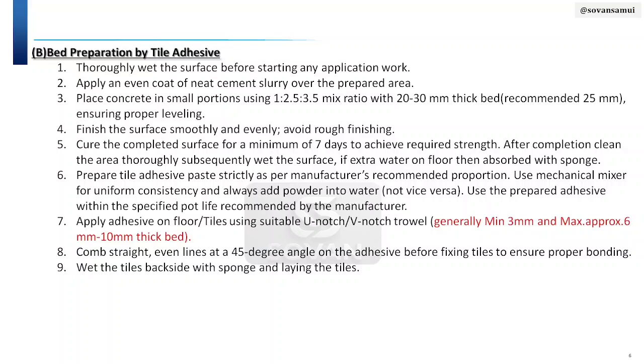Then first apply a neat cement slurry coat over the prepared area. After applying the cement slurry coat, we place the concrete, and concrete should be 1 is to 2 is to 4 with 20 to 30 mm thick bed, according to your requirement.